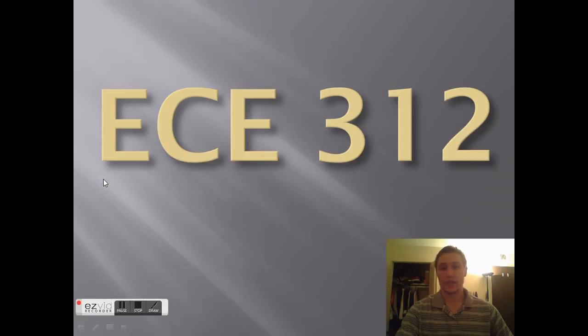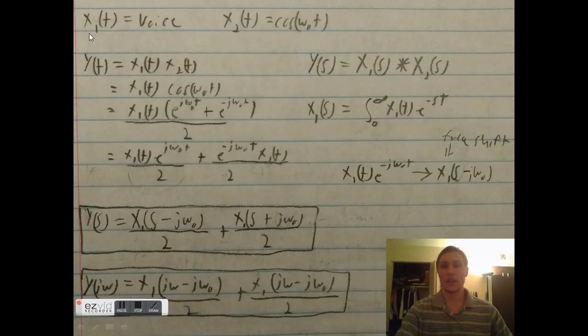Now, for the first class, it's going to be ECE 312. Right here is a mixer. This is what's happening in the waves. x1 of t is equal to a voice signal, x2 of t is equal to my carrier signal. Now, cosine of omega t can also be split up into two complex exponentials, e to the j omega t plus e to the negative j omega t, divided by 2.